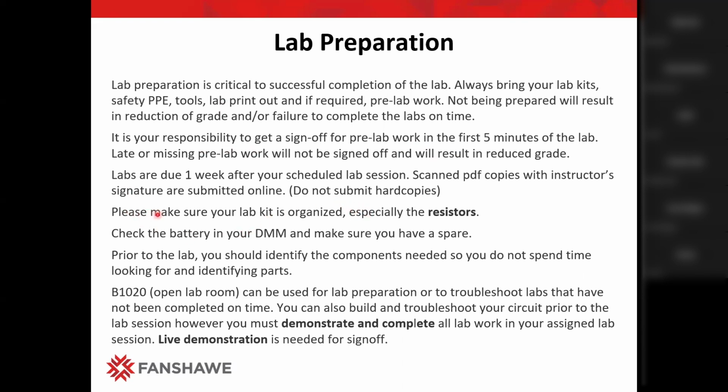All right, please check machine. Be organized with it, because you don't want to lose stupid minutes looking for cables. Get your own cables, get your own probes, and for the oscilloscopes, use probes. Don't use the BNC connectors with the alligator clips. Use the oscilloscope probe. Now, if somebody is missing something, we have a little cabinet, but the purpose of that is not to give you what you need. It is your responsibility to have what you need.